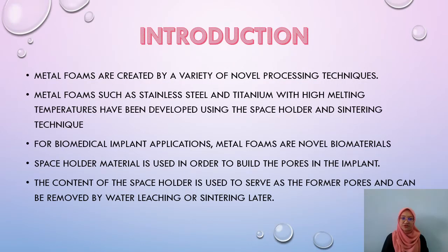Now, let's move on to the introduction. Metal foams are created by a variety of novel processing techniques. Metal foams such as stainless steel and titanium with high melting temperature have been developed using the space holder and sintering technique. For biomedical implant application, metal foams are novel biomaterials. Space holder materials are used in order to bulk the pores in the implant. The content of the space holder is used to serve as the former pores and can be removed by water